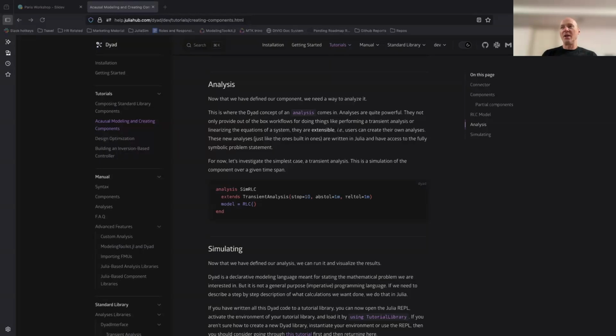I didn't point that out, but there's a whole range of nonlinear solvers and a huge collection of differential equation solvers under the hood that are suited for different purposes. That's also an advantage that we have. It's not a one-size-fits-all thing where we're just trying to do everything with something like DASL. In fact, Chris and I were recently discussing the fact that for fluid systems in particular, he felt that explicit solvers were in general going to perform better than implicit solvers, but implicit solvers tend to be the default in the Modelica world.